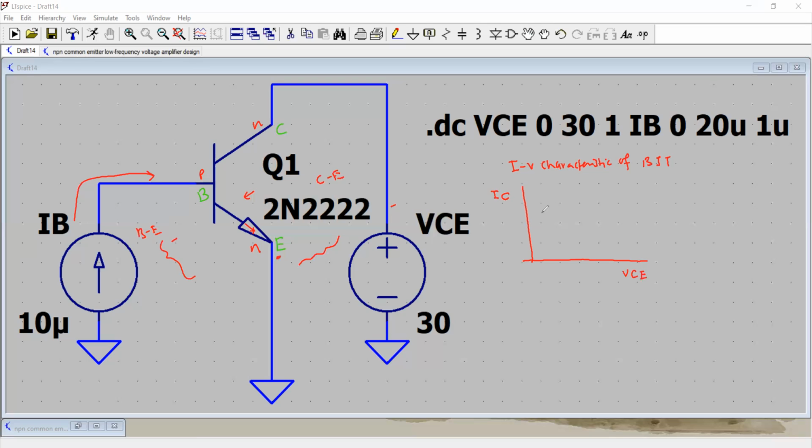So when you do discrete electronics design using BJTs, FETs, MOSFETs, etc., when you use a transistor, you basically need to know the Q point, also called the bias point, or the operating point. You need to know this to set up DC biasing. Here in this circuit, DC biasing is not shown.